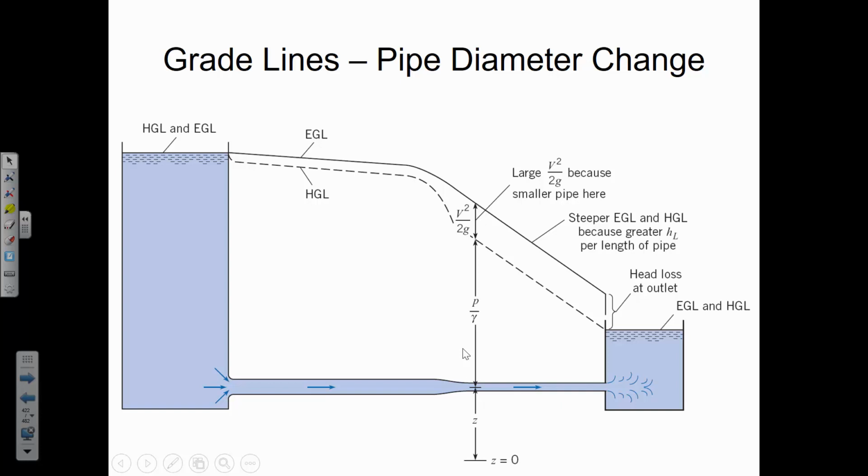Okay, I already showed you a little bit about two tanks. But in that first example I drew, it was the same diameter pipe. In this illustration, they're showing what happens if you have two different pipe diameters. You've got a large diameter pipe that's transitioning to a smaller diameter pipe. Now, flow into the pipe network equals flow out through the pipe network.